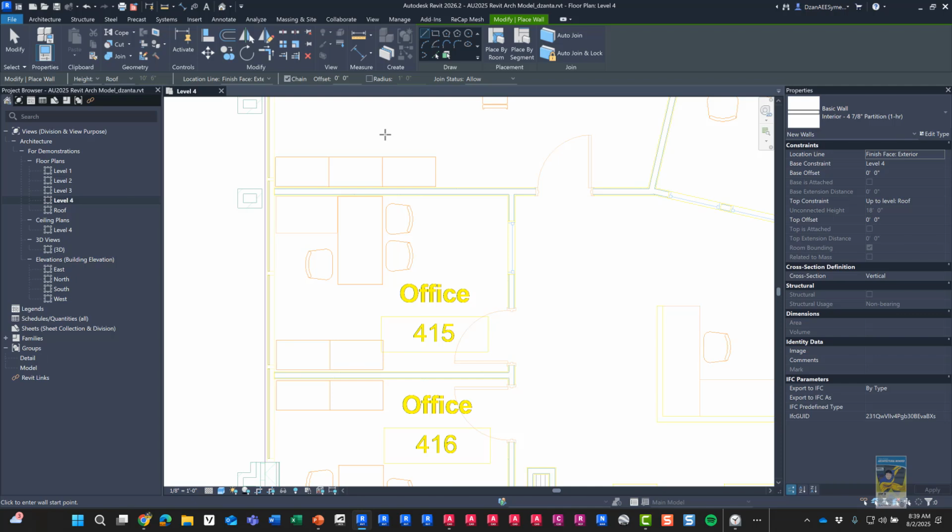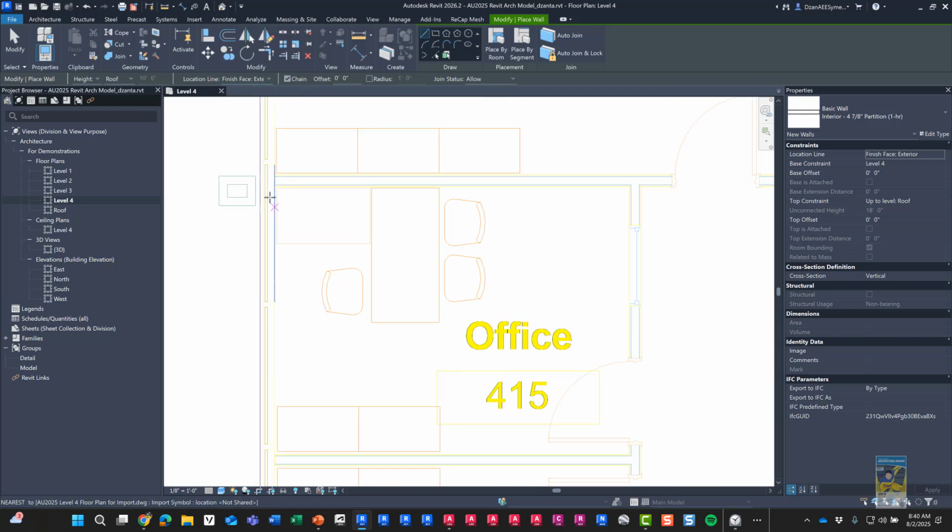If you put it up there and specify the height as 10.6, you will not see a lot of clashes from the MEP modeling and architecture modeling perspective. So for now, make sure your walls are whatever you choose. Make sure its height is up to roof. You can go here under the location line and specify what you want. And then you can start modeling.